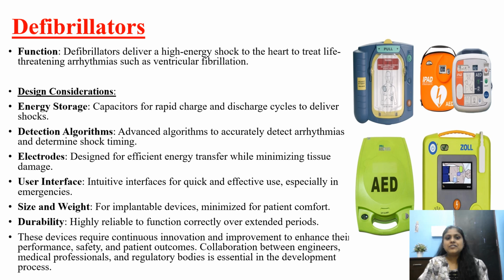Defibrillators deliver a high energy shock to the heart to treat life threatening arrhythmias such as ventricular fibrillation. Design consideration: energy storage: capacitors for rapid charge and discharge cycles to deliver shocks. The capacitors are used because a capacitor stores the charges. Detection algorithms: advanced algorithms to accurately detect arrhythmias and determine the shock timings. Arrhythmia is nothing but a problem in the rhythm or the rate of heartbeats.